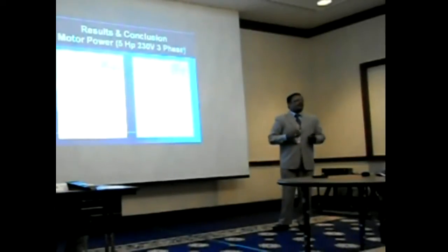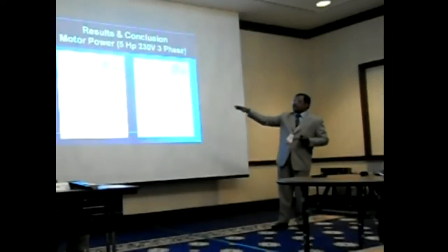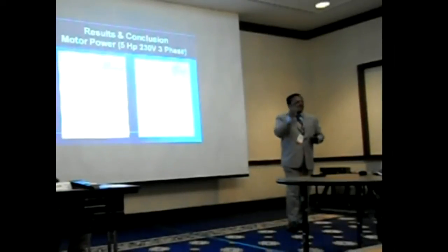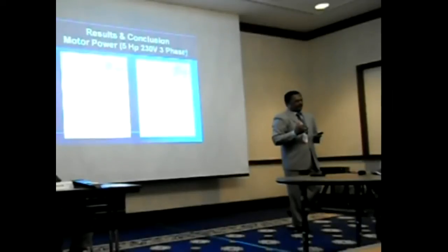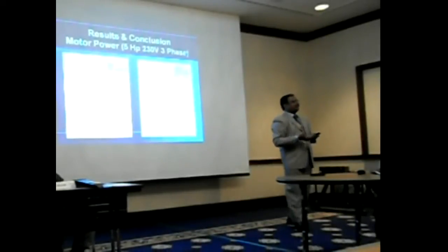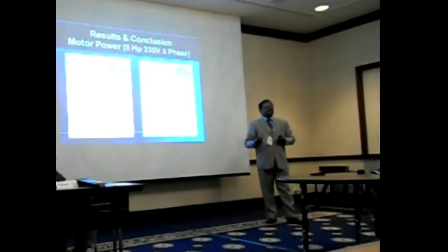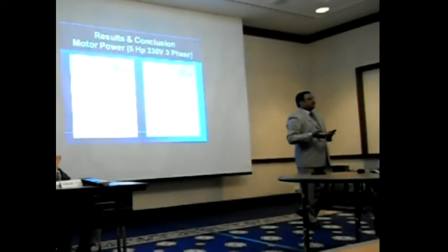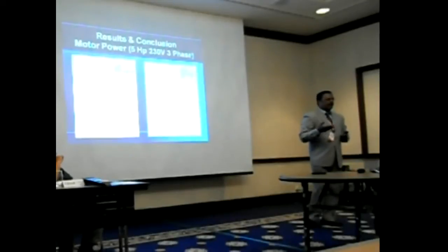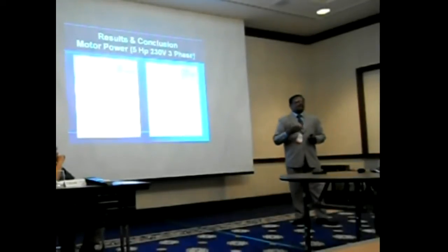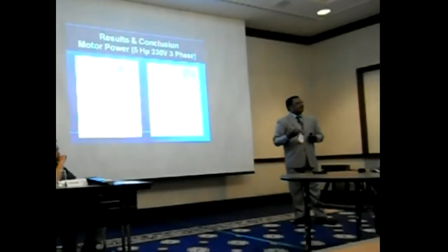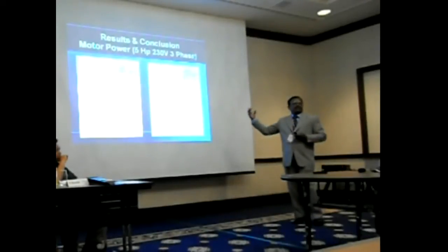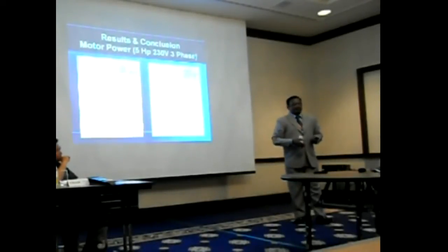Similarly, for the power consumed during starting, compared to the conventional sine wave, the raised sine wave has 20% less power consumption. That is an added advantage of the design. You will be saving energy, and for motors that require frequent starting and stopping, like lifts, conveyor belts and elevators, you will save a lot of energy by reducing the starting current.